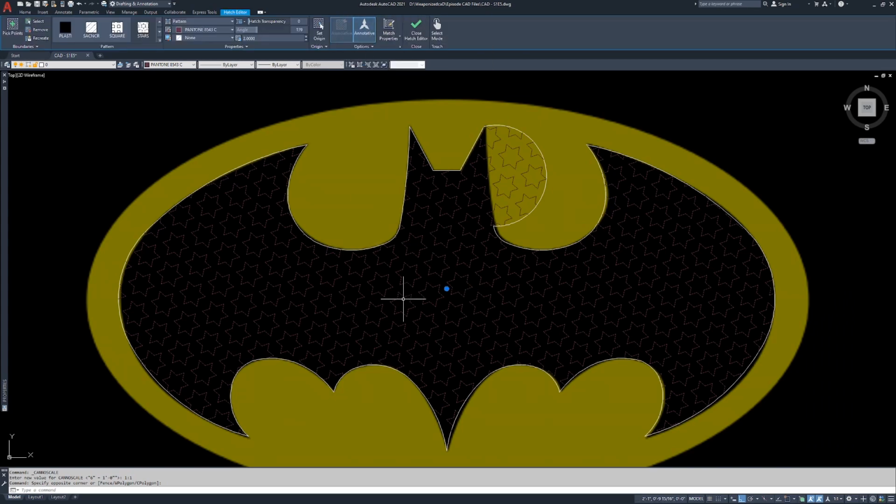And it's good for when we get into our sheet layouts and we're actually putting viewports in. We're going to be worrying more about annotation scale, things like hatches, things like dimensions, text. All of that is going to be controlled by that annotation scale. And the reason is because if we are looking at a viewport that's set to a really, really big scale, like 1 inch equals 200 feet, this hatch would be very, very hard to see if it wasn't automatically updating based on this button here.